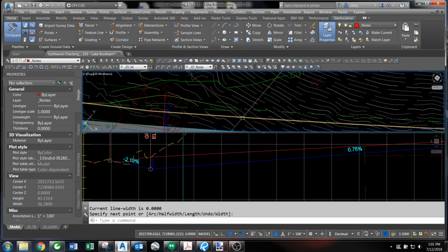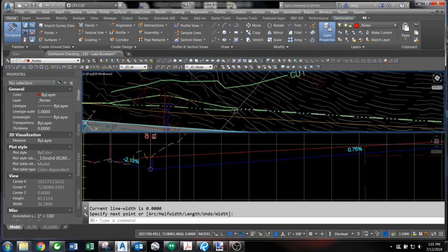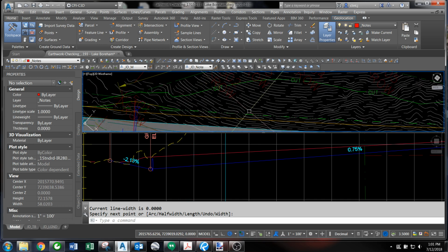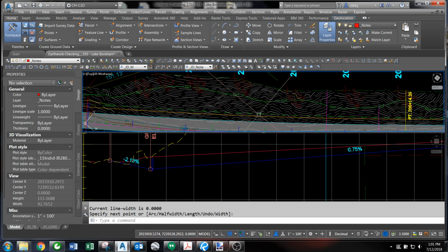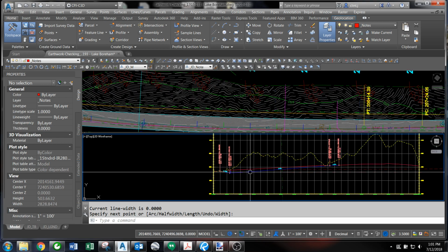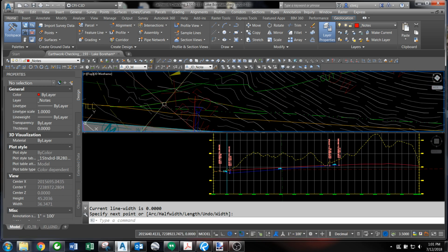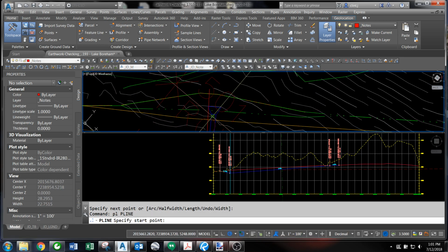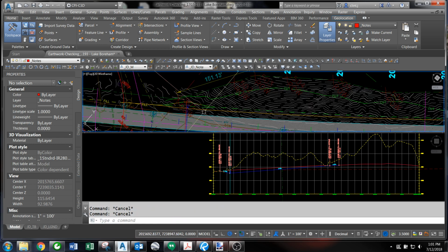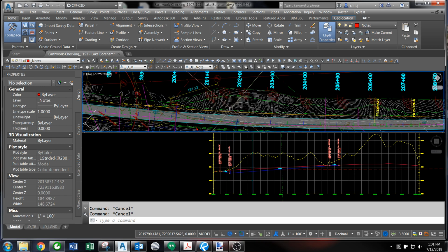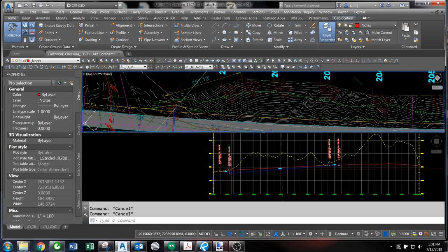So technically my ditch line should be 5 to 7 feet out from what it would have been with a typical section, because of this depth we added in order to get water to flow down to this culvert. In addition, you're an additional 7 to 8 feet to get out to where our catch basin is. It's not going to be multi-thousands of yards, but there's a significant amount of material that's going to be cut back into the hill.